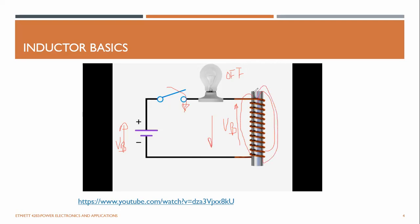Once all the flux lines are created and it is saturated, the inductor will just act as a piece of wire. It's literally a short circuit between its terminals once this magnetic flux is created. So all the current can now flow through the light bulb. With a piece of wire the voltage is 0, and the battery voltage goes across this light bulb. Initially all the voltage goes to the inductor as its inductive field is created. Then it acts as a piece of wire, and the voltage is transferred back to the light bulb.